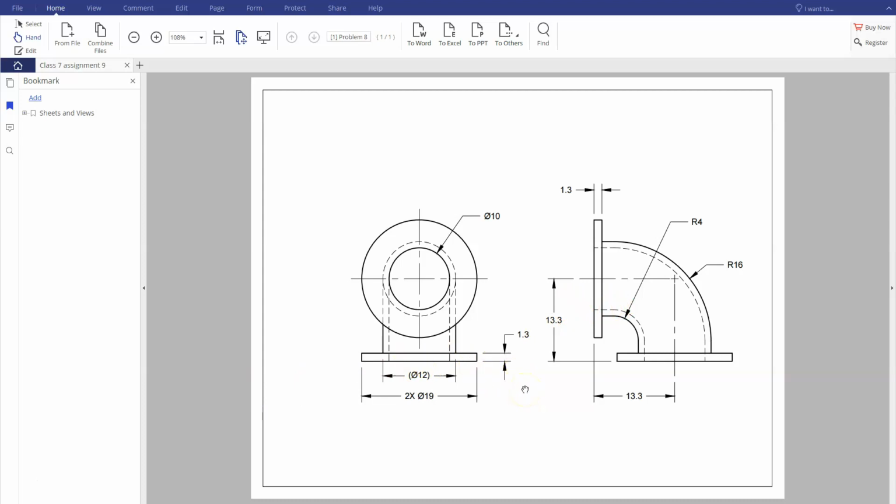But everything else on here should be more or less self-explanatory, except you want to make sure that these dotted lines that are showing the inside of these pipes are offsets from these, as opposed to doing a circle with a radius of 16. So you want to keep it nice and smooth as whatever fluid or air is going through this. So that's why we're going to use the offset when we get to looking at these arcs.